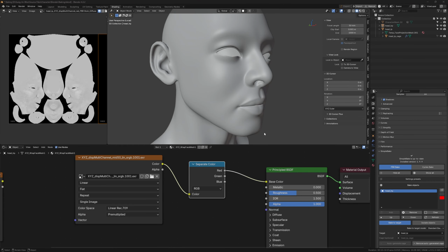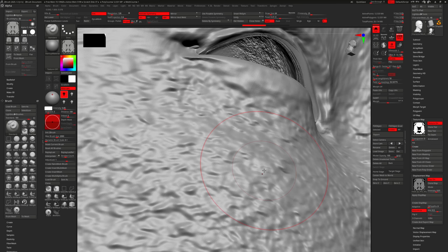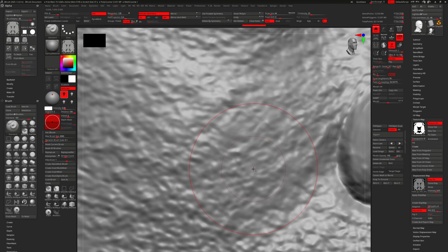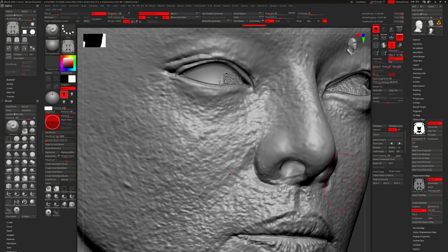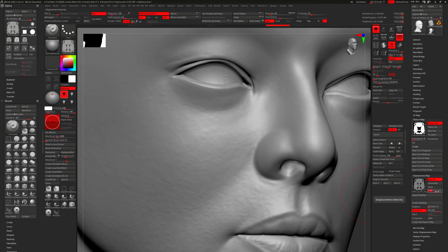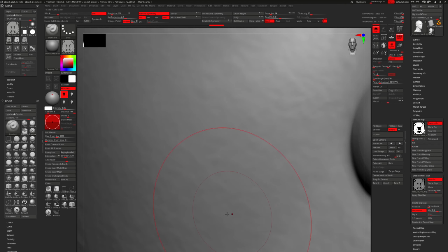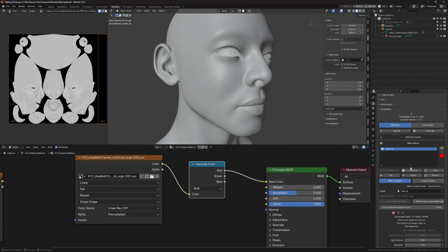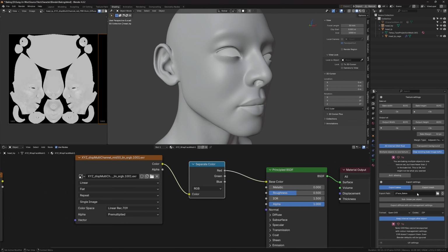Okay, I actually found the issue, guys. So I'll show you the new bakes. The new bake has this result. So as you can see, the stepping is gone. Now I'll just have to keep a proper value. So when I was baking in Blender, I didn't turn on the internal 32-bit float.